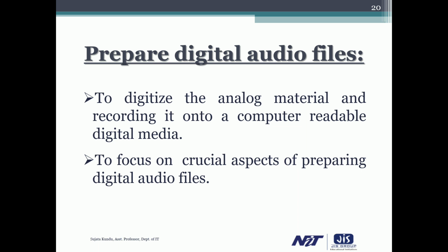Remember that the sampling rate determines the frequency at which samples will be drawn for the recording. Sampling at higher rates more accurately captures the high frequency content of your sound. Audio resolution determines the accuracy with which a sound can be digitized.